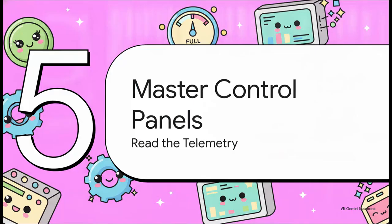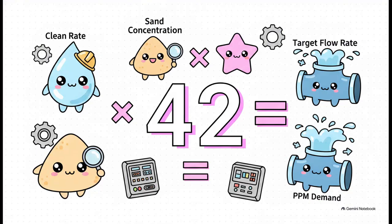And finally, Section 5. Master the control panels. 42. No, it's not just the answer to the universe. It's the golden formula powering your entire demand logic. To calculate the target flow rate, the system takes the clean rate, multiplies it by the sand concentration, and then multiplies that by 42. That final number you get, that is your exact target pounds per minute.